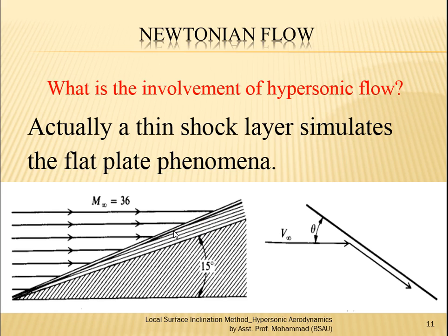The shock is so close and so near to the solid surface that if you have a macro view looking from outside, it looks like the flow is actually coming and attacking the surface rather than getting turned by the shock itself. So it attacks the surface and then becomes parallel to it. And no doubt the flow in the shock layer is parallel to the solid surface of this wedge. So this is very similar. What we see here is it attacks and then becomes parallel. A similar thing is happening here.